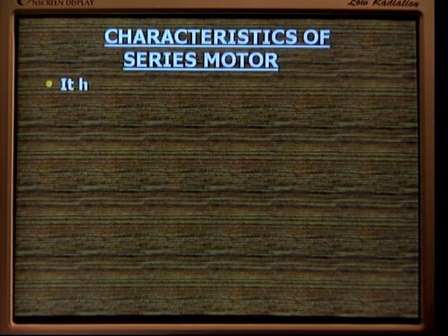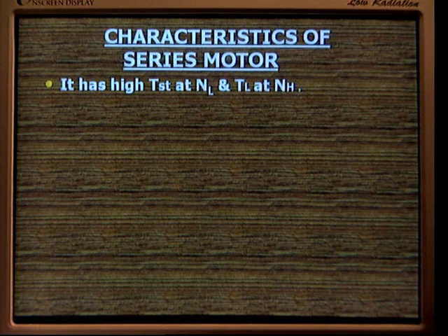Why should we use this DC series motor in traction? Because it satisfies a number of requirements of traction. What are they? We can see them one by one. Characteristics of the DC series motor: it has high starting torque at low speed and low torque at high speed.